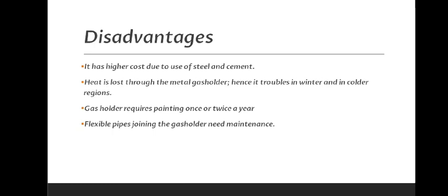Disadvantages: it is a higher cost due to use of steel and cement. Heat is lost through the metal gas holder, hence it has troubles in winter and in the colder regions. Gas holder requires painting once or twice a year. Flexible pipes joining the gas holder need maintenance.